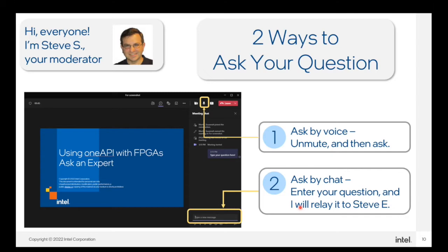The Lite Edition supported Cyclone 10 LP, as I thought, and the other Cyclone devices, 4 and 5. Arria II is supported, but not Arria V or 10, of course, and then all the Max devices. So it's in the Lite free edition. It's all the low-end free stuff. But Stratix starts with the Subscription Edition. Okay, all right.